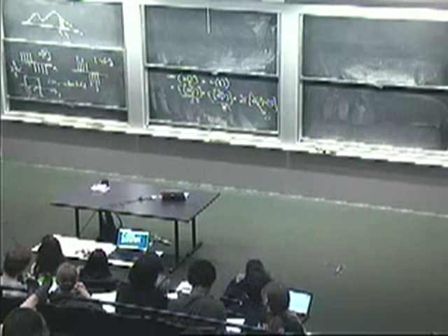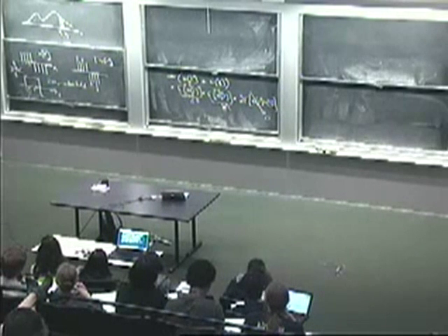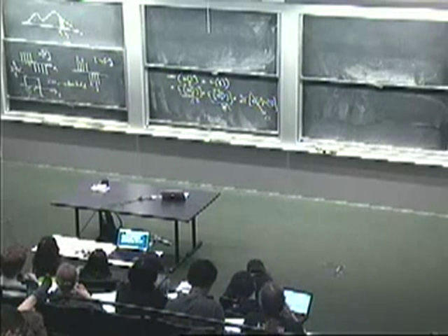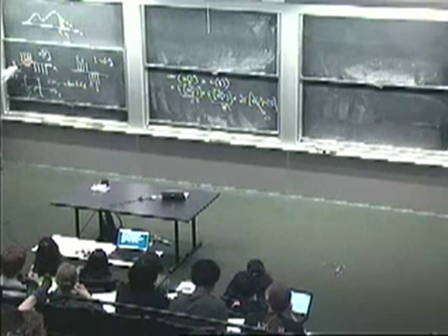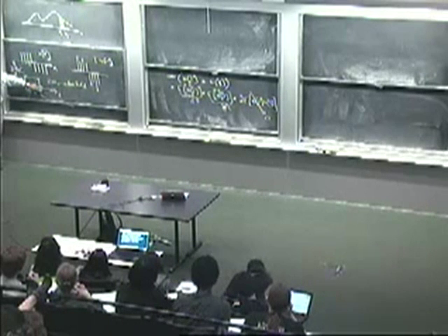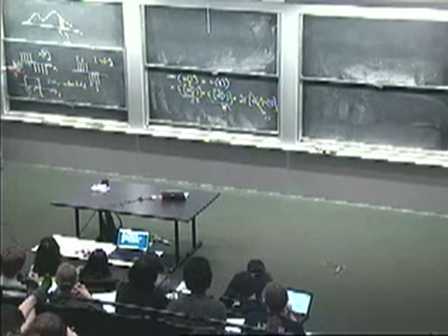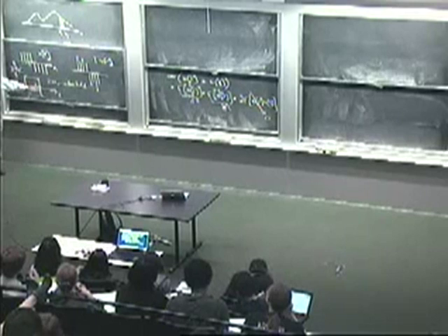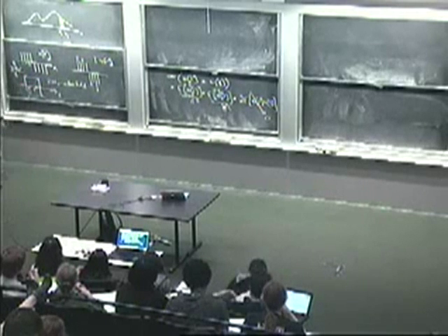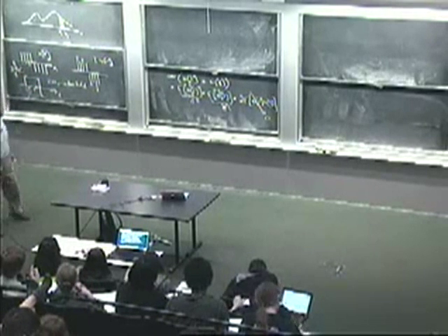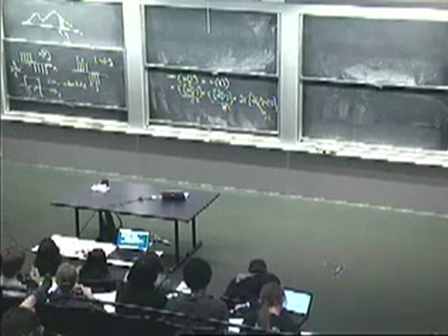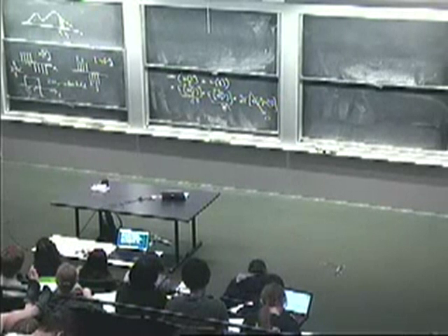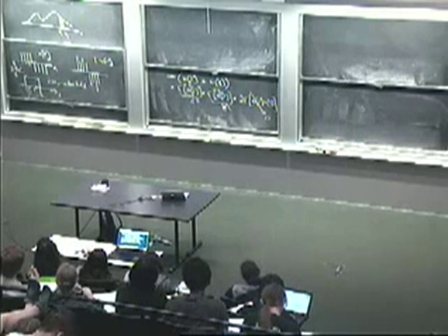So what I want you to imagine is that when we get to the DAC finally, it's going to be something like this. So all my pictures will be discrete time sequences, and I won't say much about what goes on here. So I want you to imagine that whenever I have a sequence like this and then I end up putting it on the physical channel, there's been a conversion of this type. Okay? That's what your D2A card will do in the computer at this point. So you feed it a bunch of numbers, you give it a sampling rate or a reconstruction rate, and then it does this kind of interpolation.